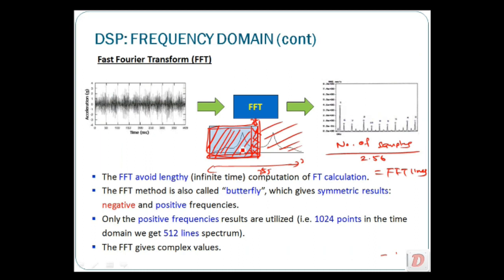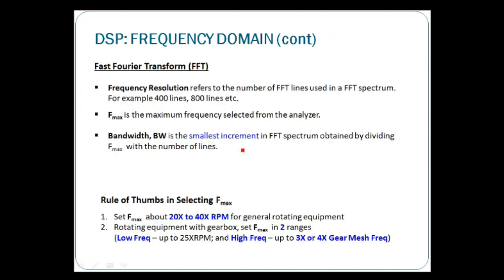Then that half won't be useful. It's just a mirror image of it. And because of the oversampling factor in the analog anti-aliasing filters, it also doesn't give you exactly half. It's only divided by 2.56. So similar things.